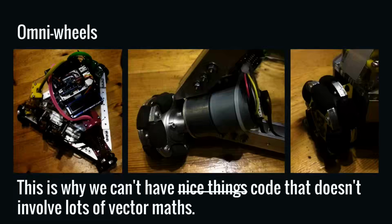If your wheel is moving forward, typically if you have a bicycle or a car, the wheel will move forwards, and if you try to push it sideways, it will skid, because it's clearly not intended to do that. Whereas with this, the rollers that make up the wheels allow it to move freely in that other axis of motion. That's why we can have a design like this where the wheels are all at 120 degrees to one another, and the robot can move in a straight line. If these were normal wheels, obviously all it could do is spin around on the spot. And clearly it can do more than that.